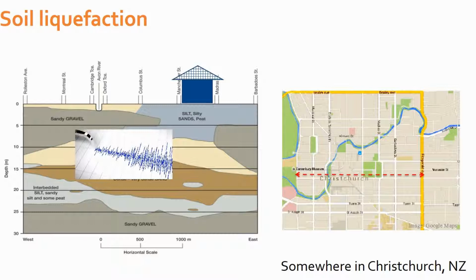If an earthquake strikes, what happens? These soils are shaken vigorously. What does that mean? The water inside those soil particles also gets agitated and gets a lot of energy. If the water gets a lot of energy, the water pressure U is going up.